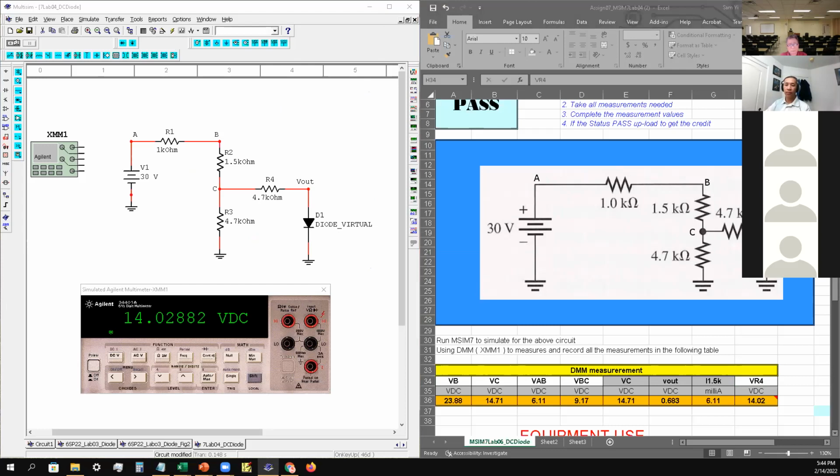Okay. Is there a difference when you go to I or when you go to H, or high? I'm sorry, what do you mean, high and low, or the ones on the oscilloscope on this meter, right? Yes. Is there a difference when you go to the high or the red, or the one where the I is all the way at the bottom? I is for current, right? I represents current. High here represents either voltage, ohm, or the diode.